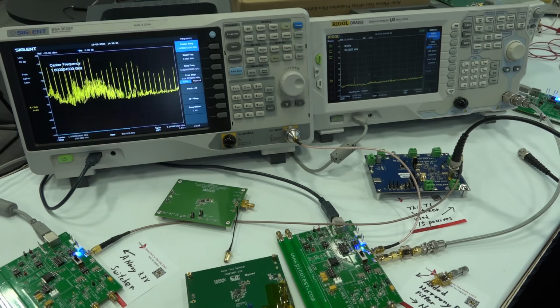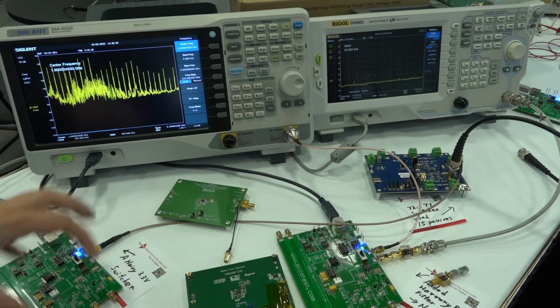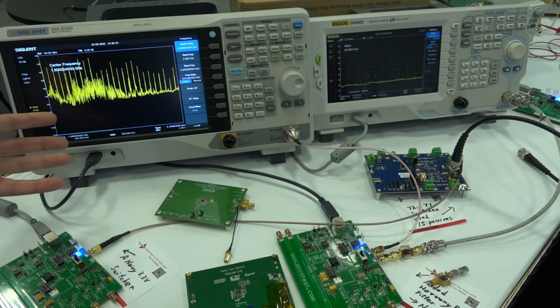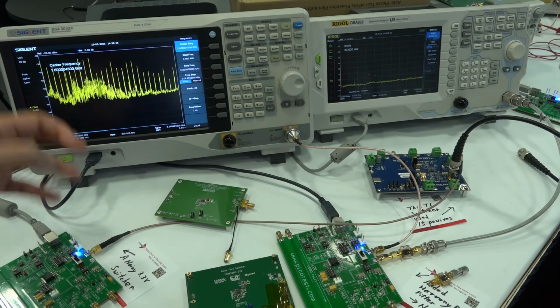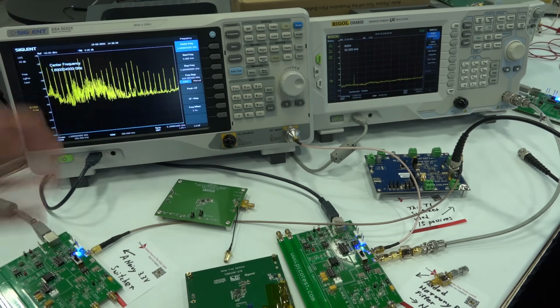So here at TransSiP, let me show you something interesting. Generally speaking, DC-DC converters obviously are going to have a huge amount of noise on them depending on the clock frequency running on the DC-DC converter. Even in spread spectrum situations where they try to eliminate some of these tones, you will still end up in a situation where you have a raised noise floor directly coming from your DC-DC converter.